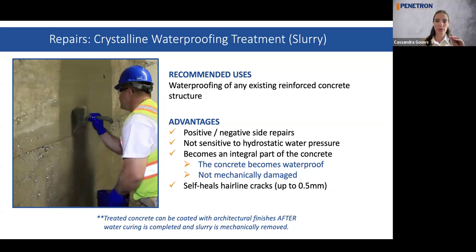So it is a treatment, very important to remember. If you do want to coat it afterwards, after the 14-day curing process, you would have to mechanically remove it. And then you can apply your architectural finish after the fact, because if you left it on and put your paint over it, your paint would most likely delaminate because of the crystal growth that actually happens on the surface.